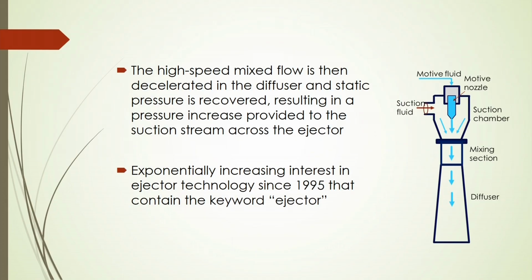And also you will see that high speed mixed flow is then decelerated in the diffuser, and static pressure is recovered, resulting in a pressure increase provided to the suction stream across the ejector. In this case you will see exponentially increasing interest in the ejector technology because of this mechanism for the formation of fine bubbles, where the gas is entrained and dragged downward through the liquid medium by that downward liquid momentum, and also getting the advantage of more surface area as well as more residence time.